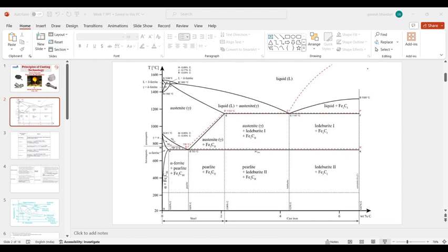Yeah, it is C, because when we talk about annealing, we talk about heating the material 50 to 60 degrees Celsius above the critical temperature, that is basically the austenitic range. Then we hold it for some time and cool in furnace. Okay, so the answer is C.